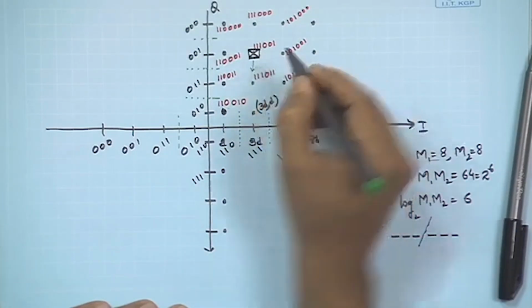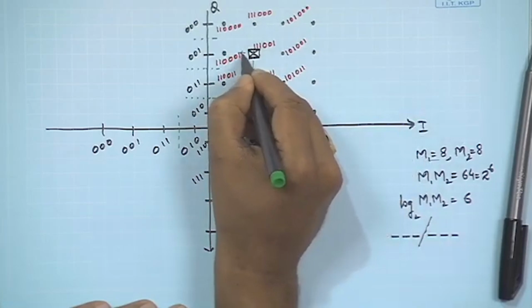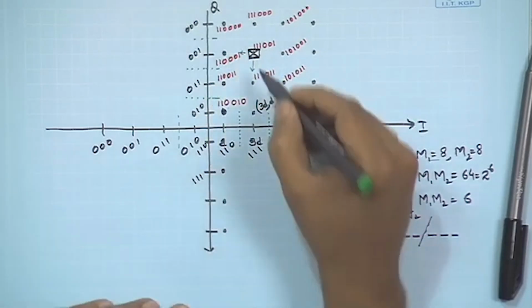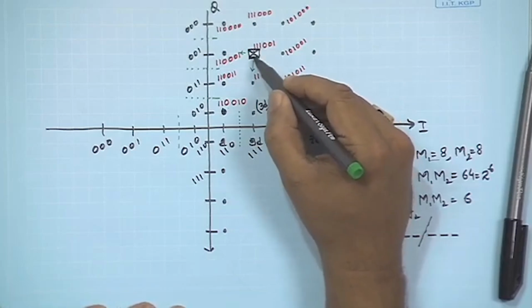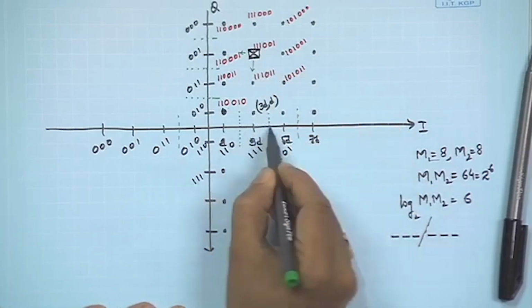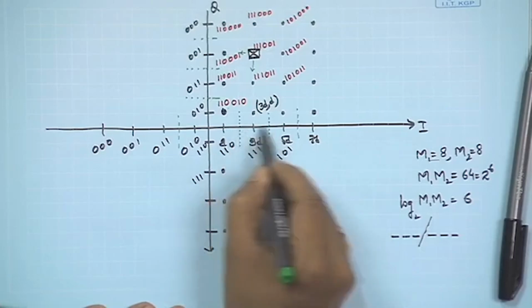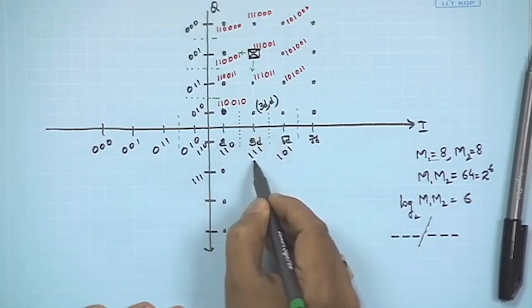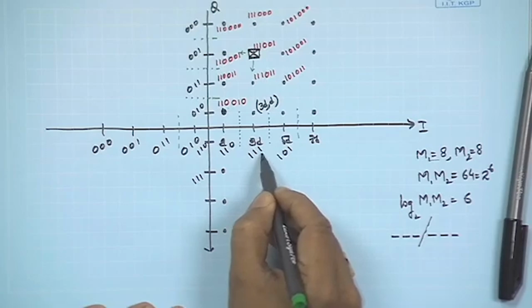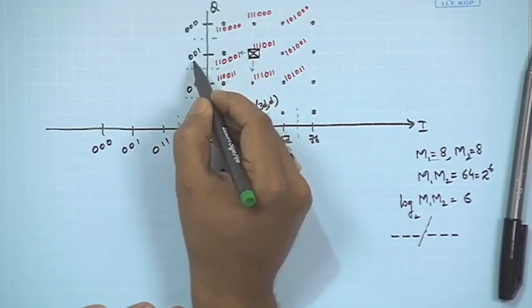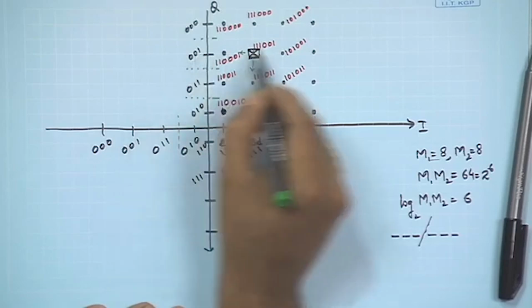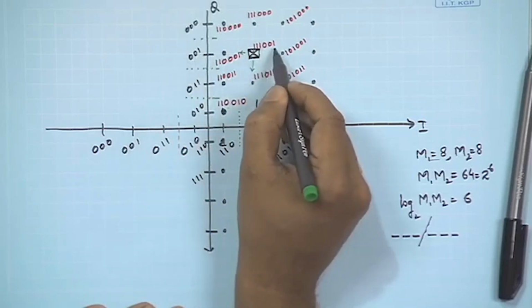So, this would go down there and on this axis it goes down there. If there is no disturbance, then this constellation would be read at the receiver to lie between this location. In this location in the I axis, the first 3 bits would be 1 1 1, and in this decision boundary the second 3 bits would be 0 0 1. So, you have this combination decoded.